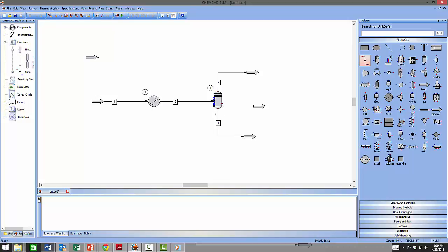The reason we have 2 liquid connections is that it becomes very helpful when you have 2 liquid phases in your system, where you can connect the heavy liquid at the bottom and the lighter liquid somewhere here in the middle. At this point, it does not really matter where you take the liquid, because there's only one liquid phase. We can bring this outlet stream for the heat exchanger cooling water down here, so that it becomes easy to connect.